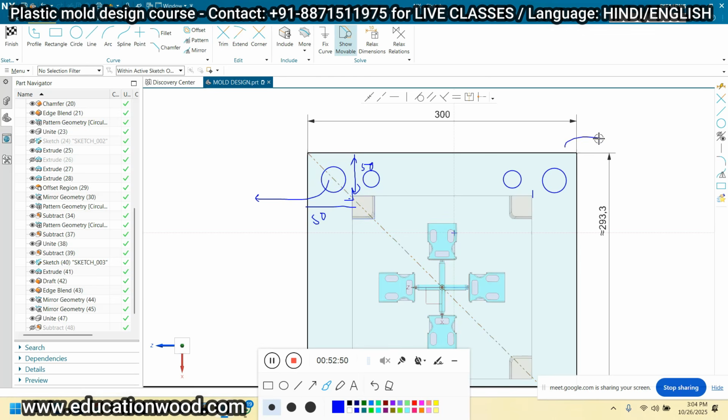By the calculation, for example, if your mold size is about 300 by 300, generally you will calculate the diameter of this guide pillar. It is around 22 or 24 mm or 25 mm, right? And this is the feature. From one feature to another feature, the distance should be 15 to 20 mm. So 50 mm from this side to this edge is feasible, right or wrong? All the other components will be in this space.